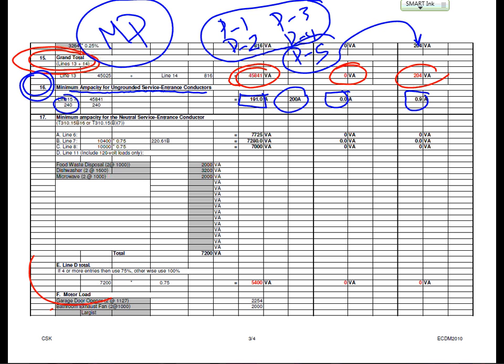From the size of the panel, guys, when you size, I have an example with you now. When I say I sized it, you size three things. Number one, the panel size. Number two, the overcurrent protection device size. Number three, the conductor size. Like you have been doing with me, when they say size, it is not enough. Oh, what did you size?